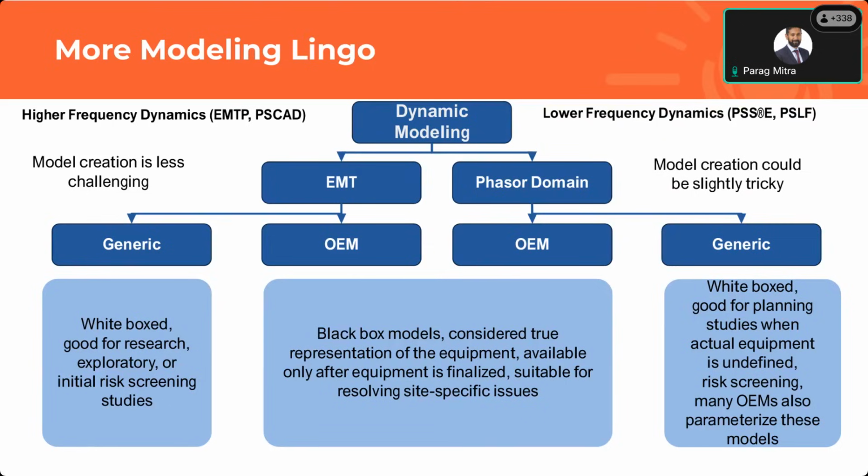Now, within both phasor and EMT models, you will find OEM models. OEM models are generally a truer representation of the device at hand. These are generally black box because OEMs want to protect their IP, so they're difficult to understand a little bit, and you might need help from the OEM to actually tune these models. But these are very well suited for resolving some of the site-specific issues, provided that these models have been developed to a certain quality that they can identify those issues and they can help you with the resolution of those issues.